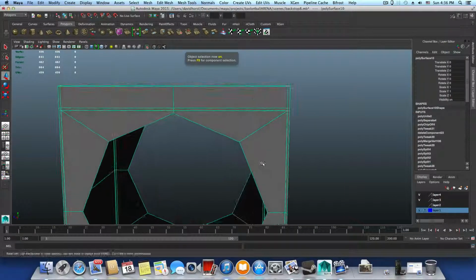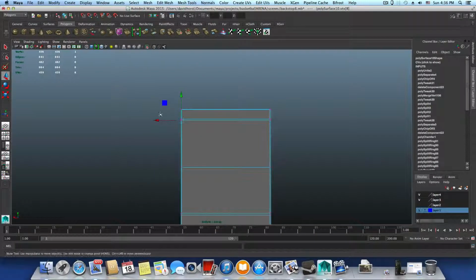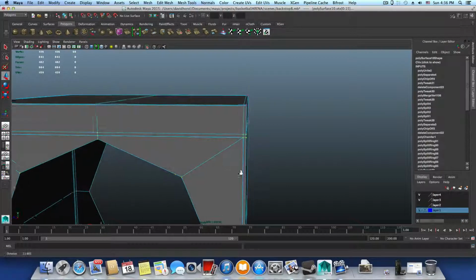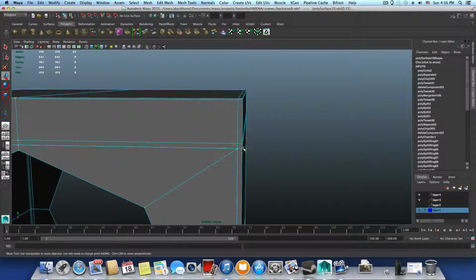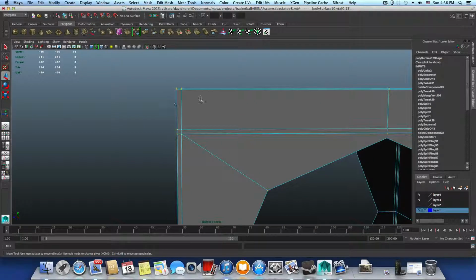And I'm gonna right click, choose vertices, and I grab all the vertices on this side. Now I want to try to avoid vertices that are unneeded to be selected. So these unneeded, these unneeded. I need only those two here at the corner. I don't need this one, and I don't need this one. So Control to unselect those. I don't need those. I don't need those.